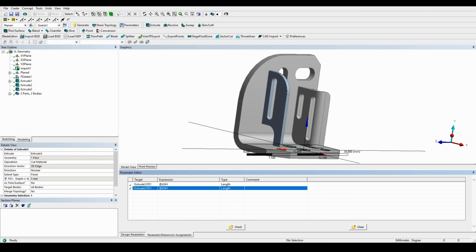Okay, once you've done that, you can then keep that parameter. The function I've just entered references the dimension of extrude FD1, used to define the amount by which the bracket extends upwards, and then you can use that later on to make references and do some amendments. Filling in the existing fillets and inserting new parameters for new fillets can also be done.